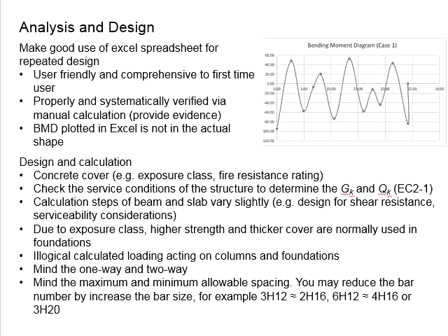As you know, normally the loads are given in terms of areas, such as kilonewton per meter square for both Gk and Qk. Therefore, the areas covered by the structural element can be a good reference for you to have an idea of whether the results calculated from the solutions are logical.